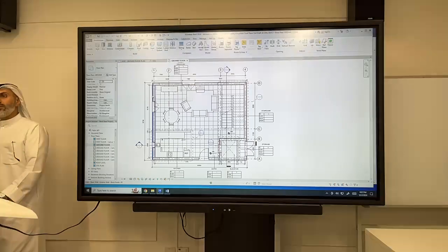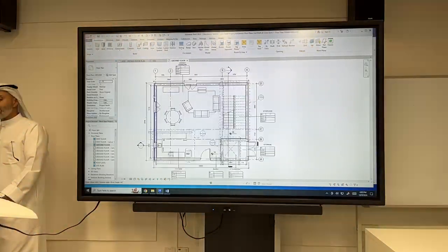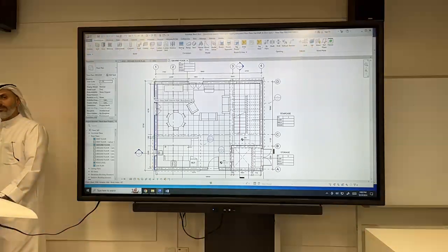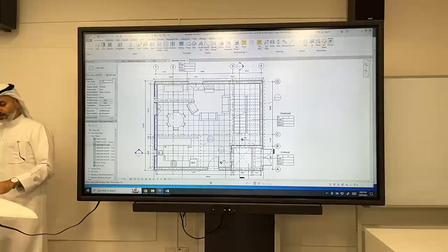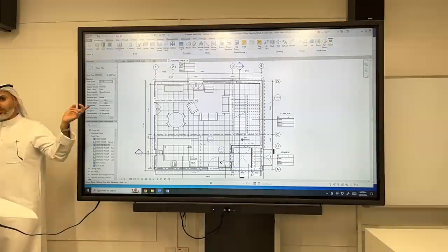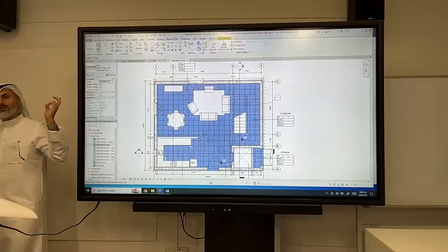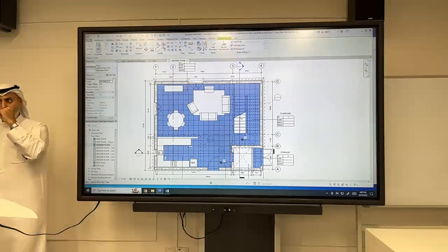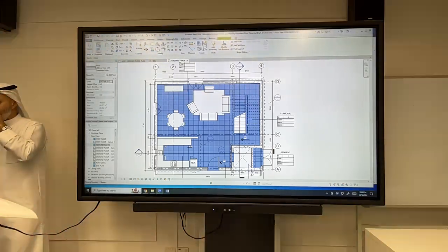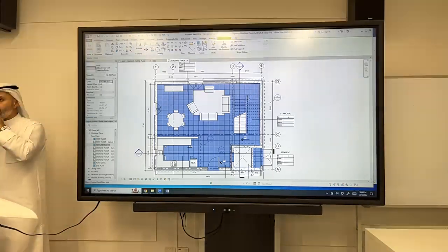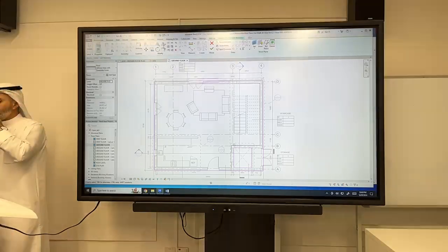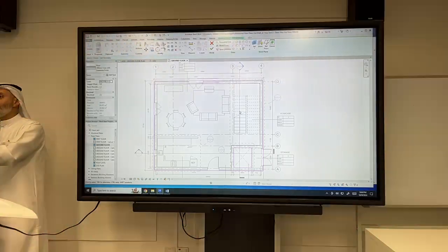So to select the floor, the ground floor, it goes all the way to the outside. So hover over one edge of your floor, on the edges, the outer wall, and then hit tab, probably twice to get to the floor. And then you click once, it should highlight the floor. What if I don't want it to cover the steps? You'd have to then create an additional floor. Meaning modify, edit boundary, bring it inside, and create another floor with a different pattern and the stairs.